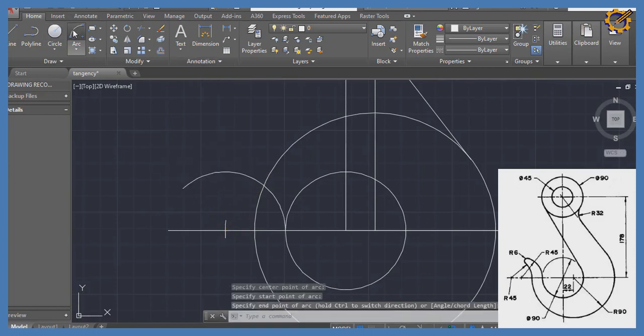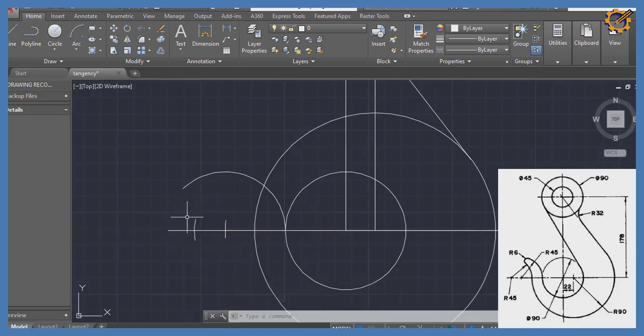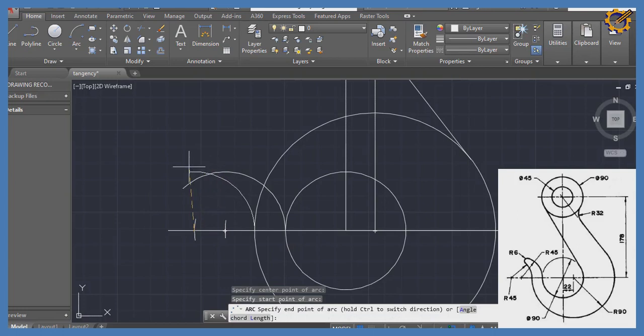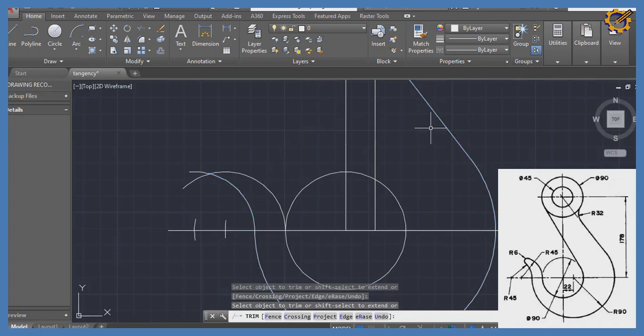So picking my arc right here also, standing right here, mark of 45. Enter. So pressing my CTRL, I'm having this. So picking my arc that same way, coming right here to this area, producing this also at radius 45. So I'm going to pick my trim command right here. This and this. Enter. So I'm trimming the whole of this. That's it. Then escape.